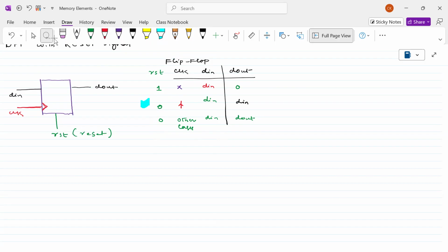Okay, that's the reason why it is called asynchronous reset. What we can call it as asynchronous reset? That means the RST is not synchronized with the clock signal. Okay, it's an independent RST actually. That's the reason why it is asynchronous. It is not synchronized with the clock signal. It is asynchronous to the clock signal. Synchronous means that both mutually must be there, then only things will happen. I don't want to consider the other thing, only I am the topmost person, then he will go accordingly, means that he is a synchronous person. Okay, so therefore it is called asynchronous reset.